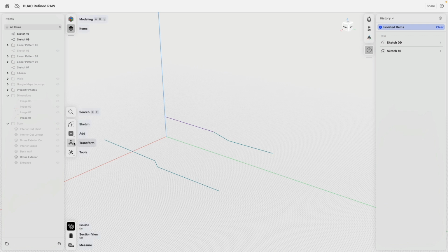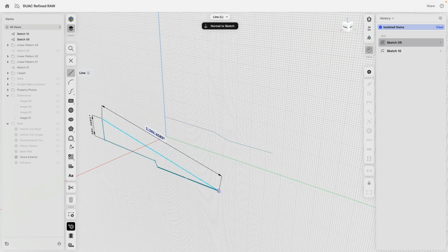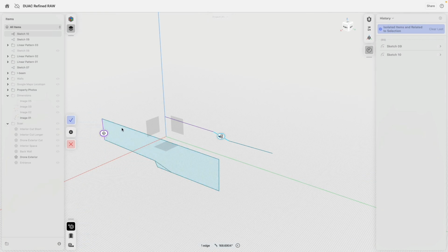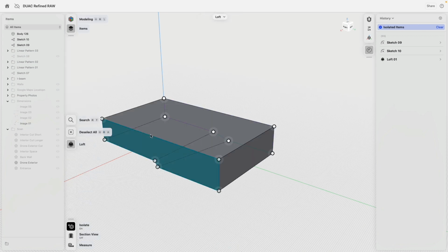And now I do the following. I'm creating a loft, but before I do this, I need to give everything a nice thickness. So here you go up, go over and go down. And then in this sketch, I simply project this over as a linked sketch. Then this I can loft.